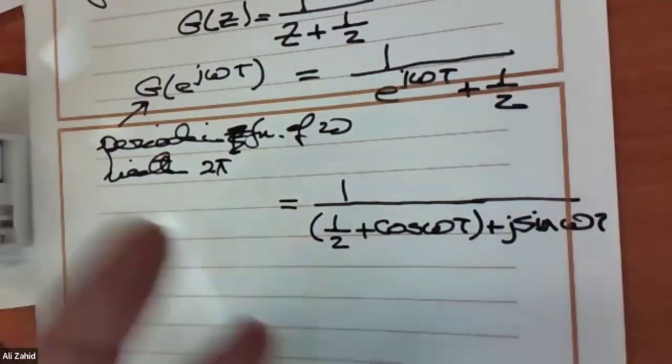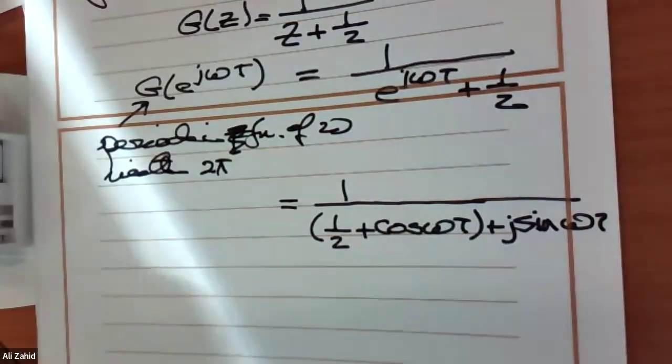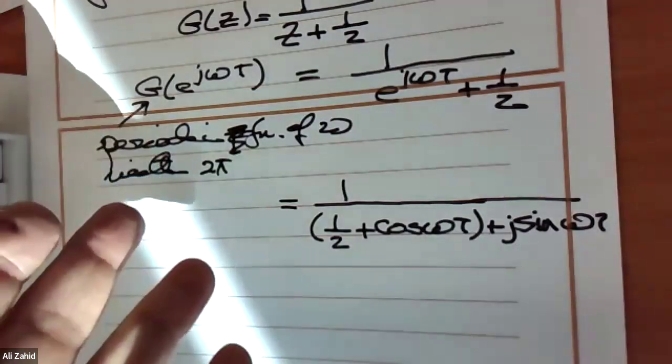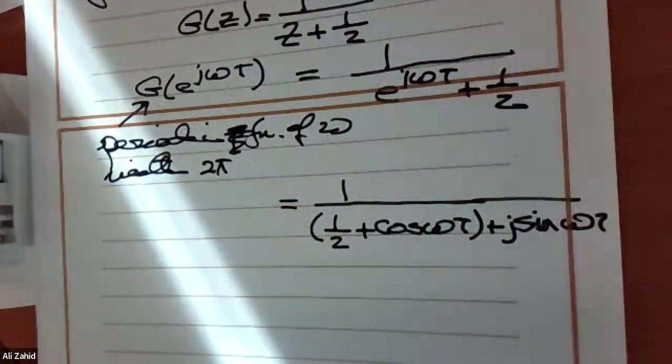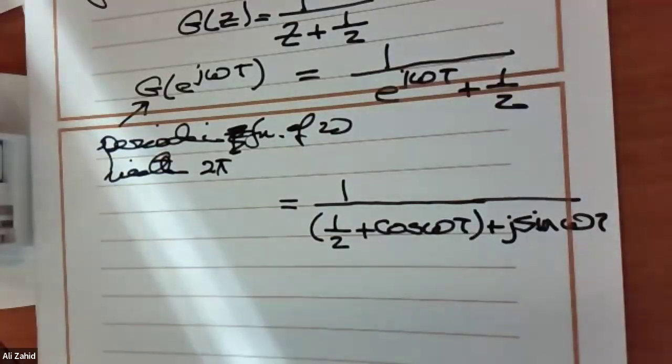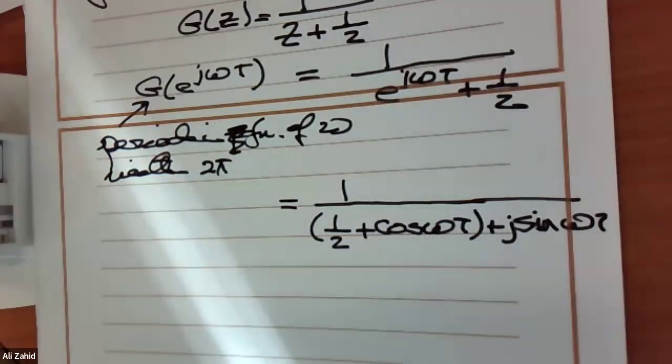And then find the real part and the imaginary part. And you do the Nyquist in exactly the same way as we did a moment ago. But the major difference is that now we are interested in C. We are no longer interested in C in the right-hand side. We are interested in C being the number of poles of the closed loop located outside the unit circle.